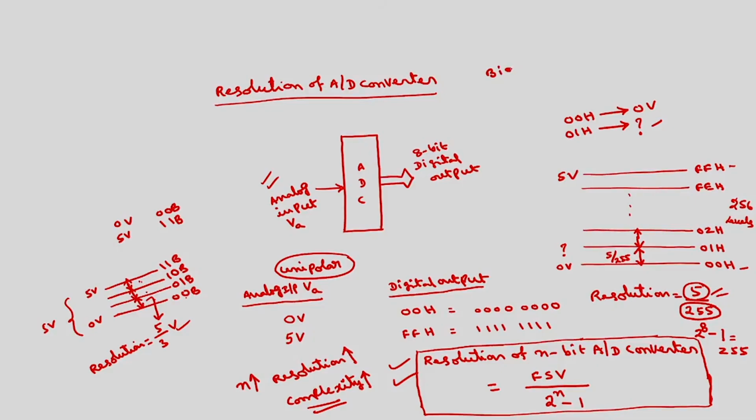So in MRI, every sample value is very important. Even if I miss a small information, it is going to create a problem. In such biomedical applications, we will use 12 bit ADCs. And if you take in general image processing applications, most of the information will be related to the background of the image, which is not important. So 8 bit ADC is also enough.